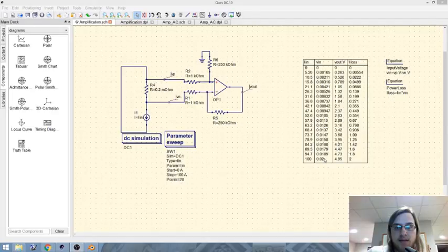So what that means is I want this 0.02 to be equal to 5 volts on the output. So it's pretty simple. I just have 0.02 multiplied by a gain equals 5. And doing a little bit of algebra tells me that my gain needs to be 250. So that's where I found my resistor values from.